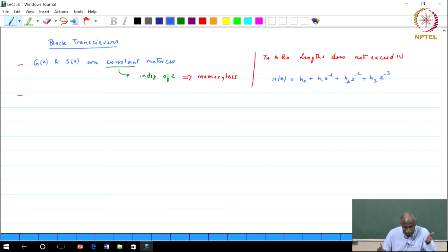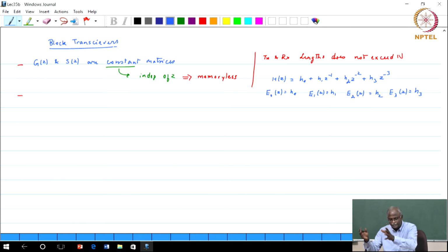Now, if I were to ask you to get me the 4 polyphase components, you would say E0(z) is a constant H0, E1(z) is a constant H1, E2(z) is a constant H2 and E3(z) is a constant H3. This is what I mean by saying that the lengths do not exceed N. As long as they do not exceed N, your polyphase components will be constants, which means that G and S are constant matrices, and therefore, there is no memory in your modulation process.